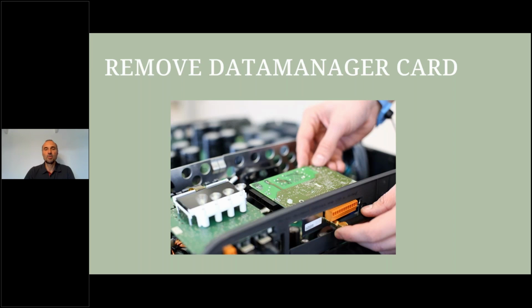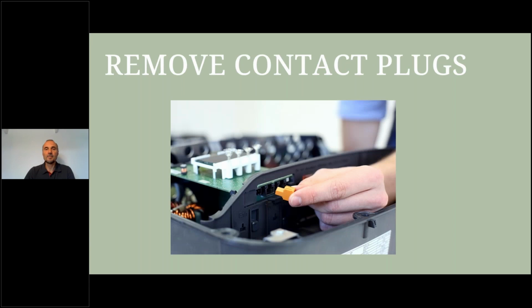You just open this 1 screw, and then you can take off the data manager card. Just plug it out and remove the card. Also, don't forget to remove the other plugs, especially the .com plug, and this orange plug is only necessary whenever you exchange the display card.